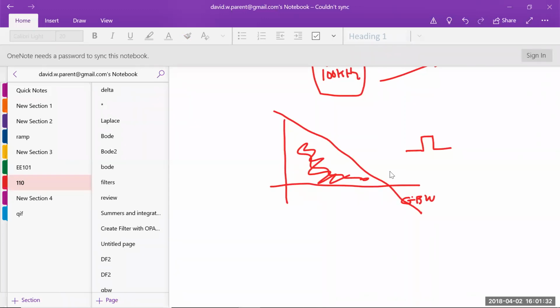All right. So even though testing with steps, or pulses, well, because with a function generator, right, you don't really get a step function, you get a pulse. You can just make this super long where it looks like a step function, right? But it's always going off and on, right? When we test like that, we're going to get these higher order frequencies, even though we might not be near the gain bandwidth. All right. Knowing why that is another reason why we studied the series.